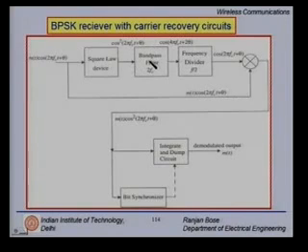Now the moment you band pass filter it at 2fc, you get cos(4 pi fc t + 2 theta). Pass it through a frequency divider to recover cos(2 pi fc t + theta). You have already m(t) cos(2 pi fc t + theta), take it here, multiply, you get back this. Integrate and dump, you get m(t) as a DC value. Right? So this is the simple BPSK receiver.